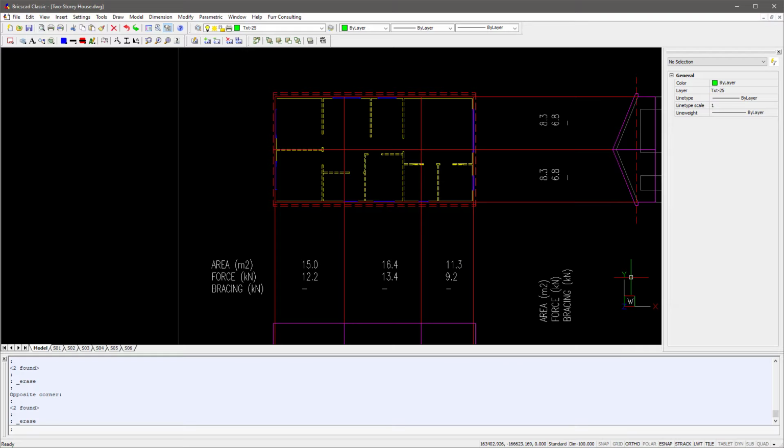So we'll start with our area on the far left here. At the corners we don't have enough room for type 1 or 2, so we'll place in 750 millimeters of type 3 at each end. We'll be showing the bracing on the inside face of the walls, however in reality they are typically on the outside. We just do this to maintain clarity of the drawing for the builder. This amount of bracing alone won't meet our force, so we'll add some type 1 at each end in these two internal walls. 1.8 meters for each should do the job.